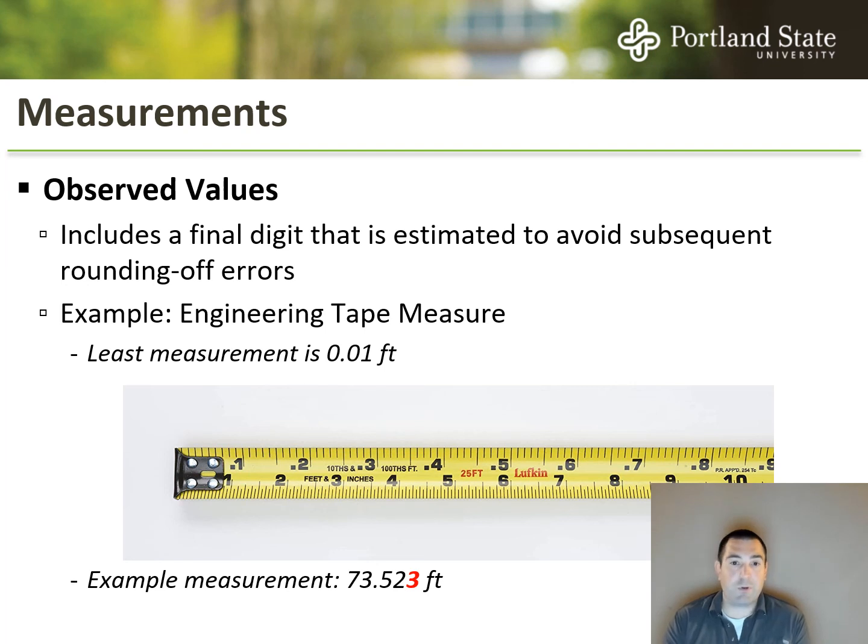That's pretty typical for engineering measurements. They're going to be in decimals of a foot, hundredths of a foot. On the bottom, you see the traditional feet and inches. That's almost never used in surveying. We almost always use decimal feet instead. And each of these gradations on that surveying side of the tape are 1/100th of a foot.